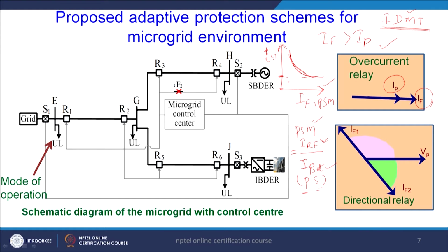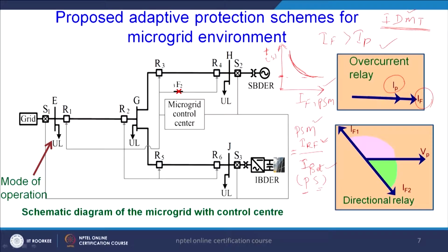Also we have the very inverse characteristic based overcurrent relay principle, or the extremely inverse type of overcurrent relaying principle, but in general in industry we prefer the IDMT type. After that, the time of operation is calculated and we maintain the TMS, that is the time multiplier setting, which is the time of operation of the relay with respect to the time dial setting.